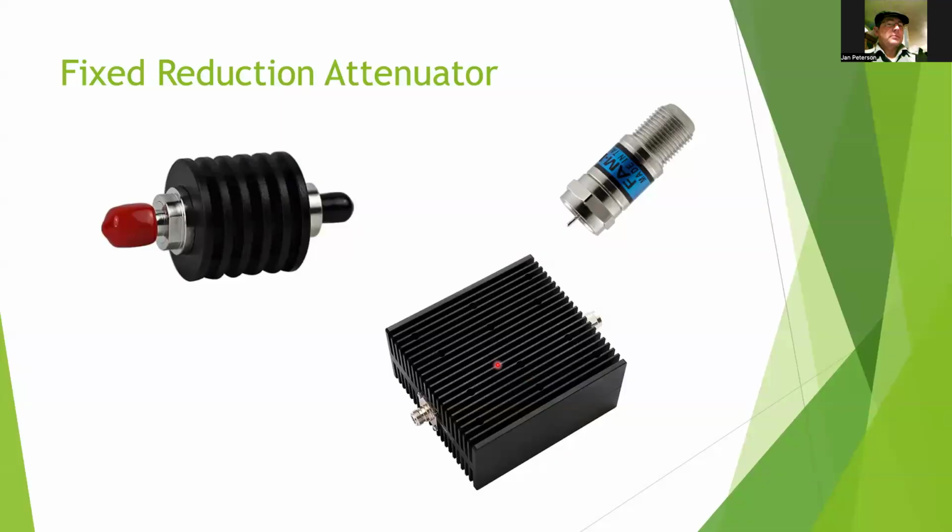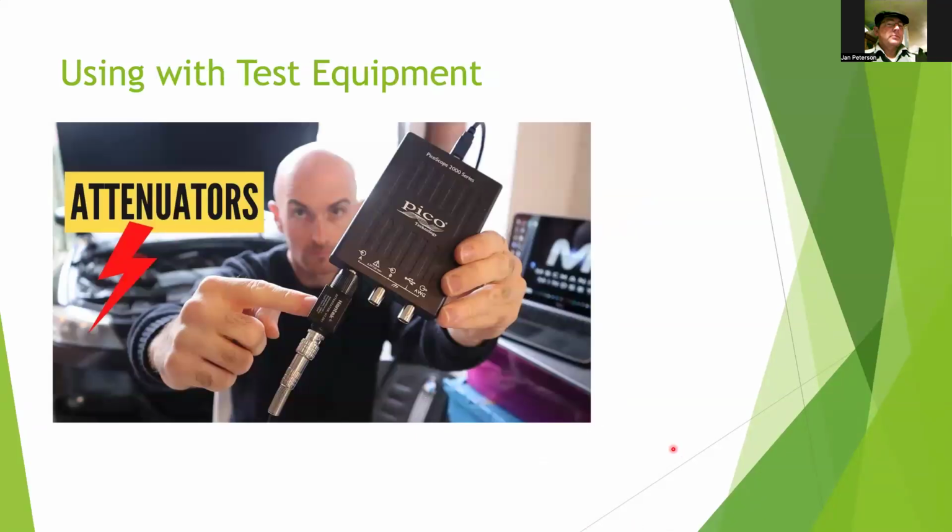Yeah. One up in the corner would be like something you hook to your handheld radio that we pack around. Where that other one would be something like we hook to the mobile, like Cadence truck. It's 50 watts. 5 watts for the handheld, 50 watts for the mobile. So you've got to select the right dummy load and attenuator for your problem.